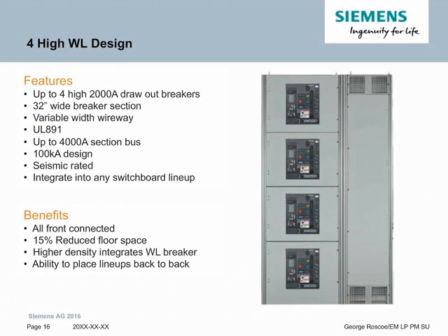Some of the benefits are it's all front connected, reduced floor space. It's the highest WL breaker density we have in front connected switchboards. And by doing this, everything is considered front access, therefore now you can place lineups back to back.